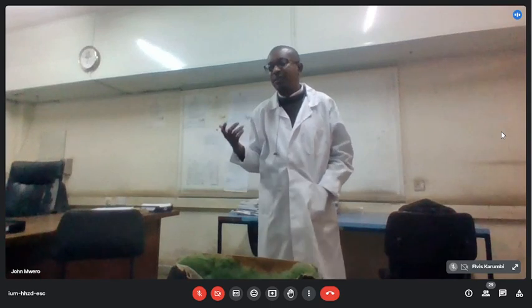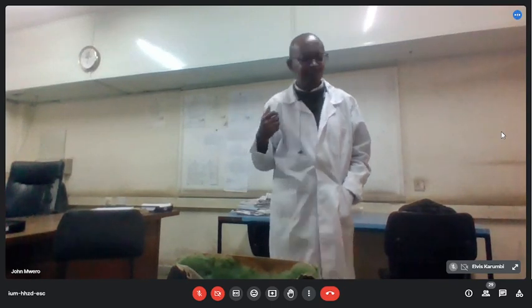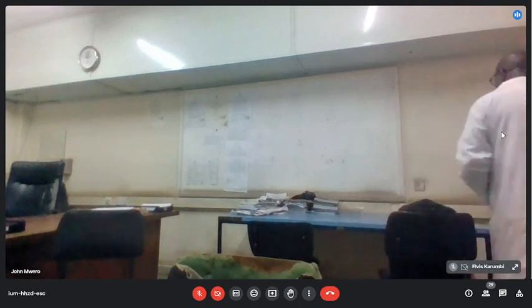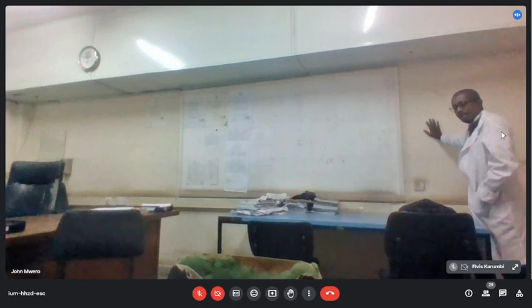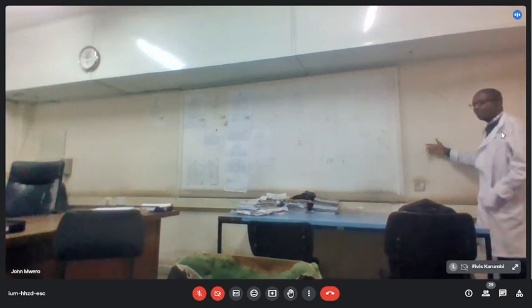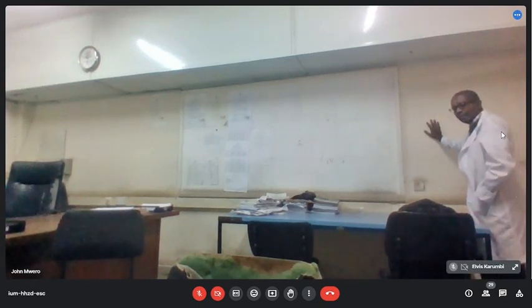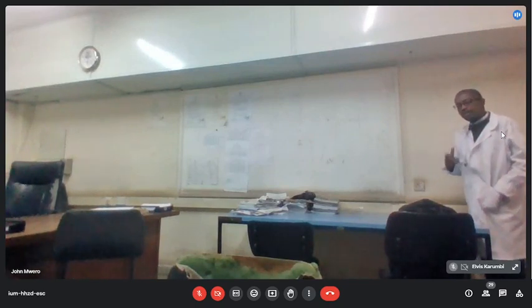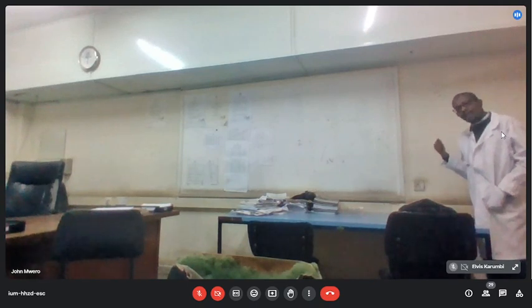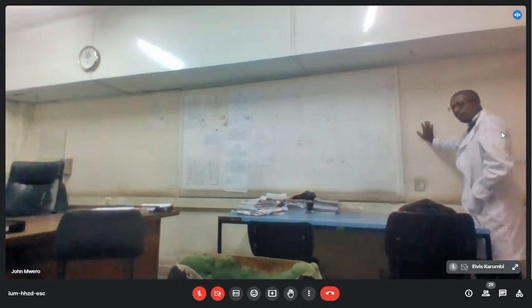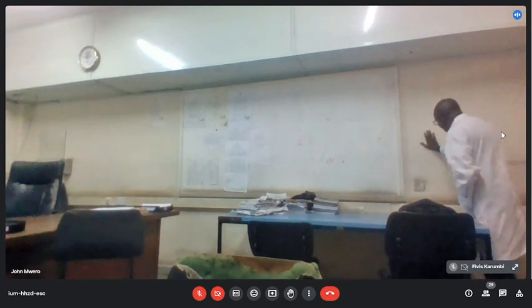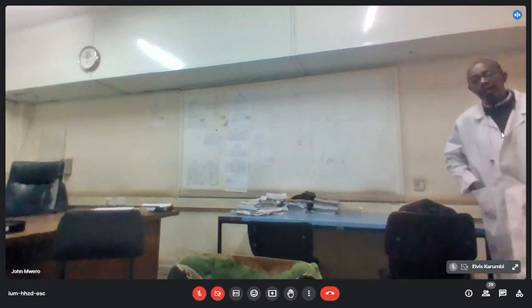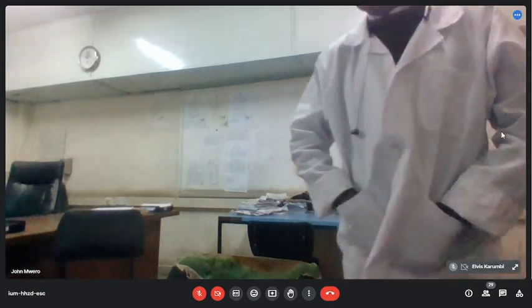Does it mean that it's not there? The truth is that the deformation is there. Back to the problem of the wall. If I push this wall, for sure it deforms. But because the stiffness of the wall is much bigger than the force that I'm applying, the deformation is so small that you might not be able to appreciate it or see it with your eyes. But the deformation is there, courtesy of that small force. And if we put strain gauges here and measured strains as I push this wall, we would actually be able to measure that deformation.